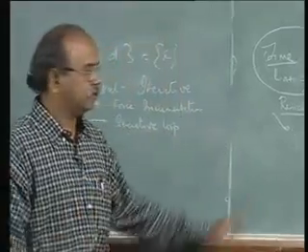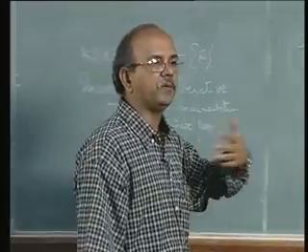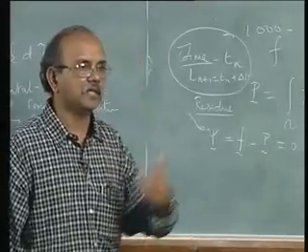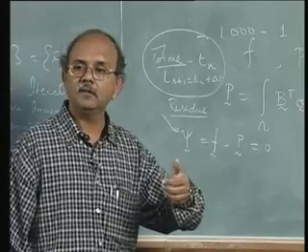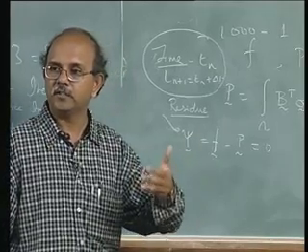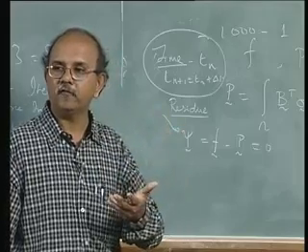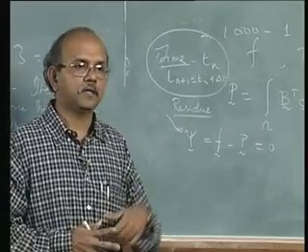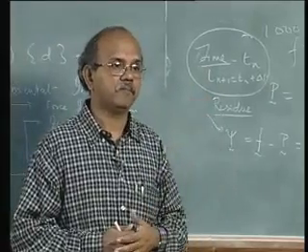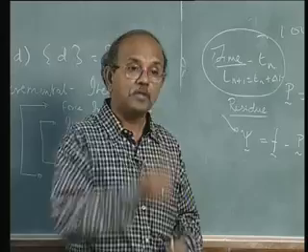If things go well, then they would watch for maybe one more step. Then they would raise delta T to be 0.2. If things go well, that means your convergence is good, they will gallop that again, maybe 1.5 times or 2 times or whatever the software decides. Then they will keep galloping it. So delta T is not a constant.